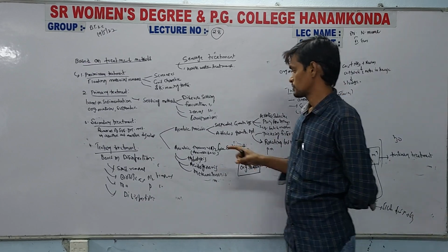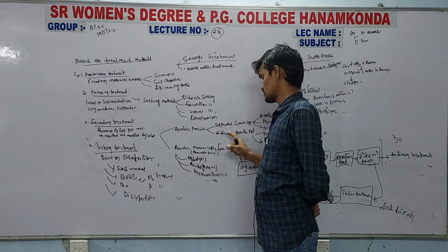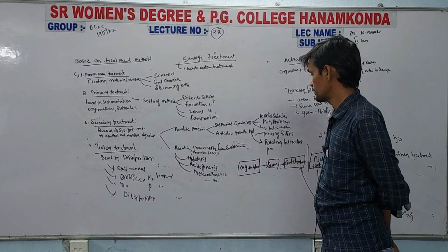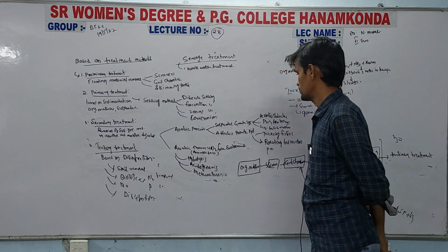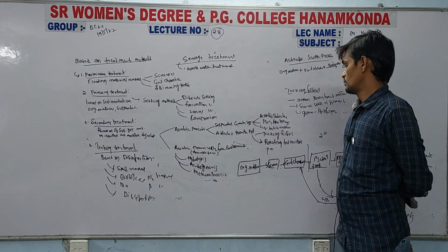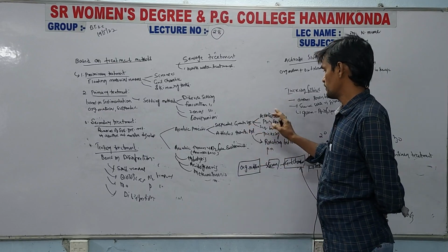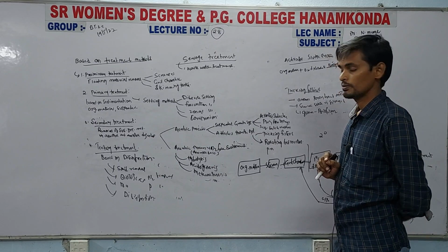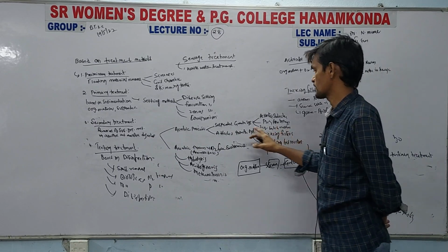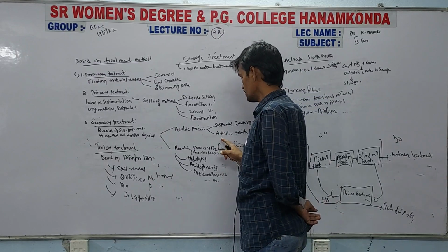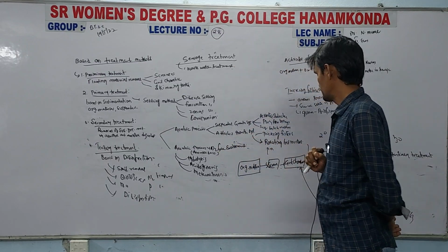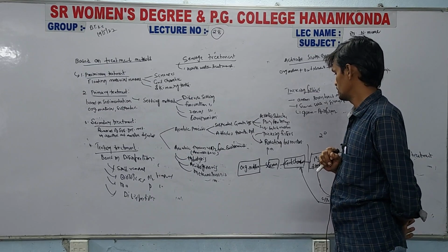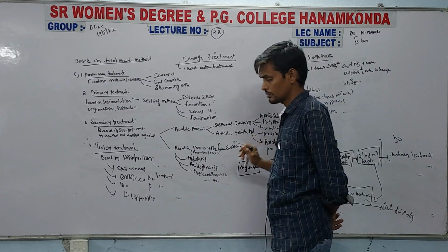Coming to the aerobic process, it is of 2 categories: suspended growth system and attached growth system. Under the suspended growth system, we have different processes, that is activated sludge treatment, plug flow system and sequencing batch reactor. Next, the attached growth system includes trickling filters and rotating bed reactors.